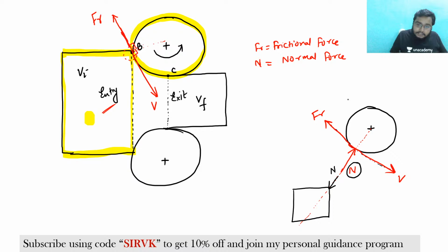Now see, frictional force is acting in this direction. So here the frictional force would be acting in the opposite direction. Clear? What is this angle? Is it alpha? Angle of bite, is it alpha? Yes, it is alpha. So if you would draw a triangle here, what you can see, this is alpha, this is 90 degree. So what is this angle? Is this angle 90 minus alpha? Yes, so that angle is going to be 90 minus alpha.